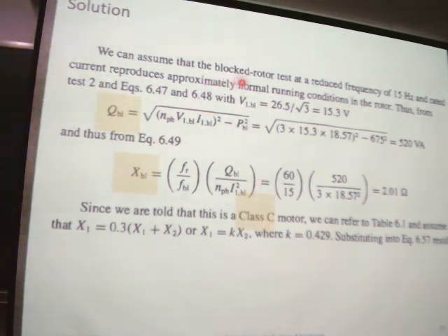Then the blocked rotor test at 15 Hertz. At this frequency we can also calculate the blocked reactive power with this equation, from the apparent power and active power.